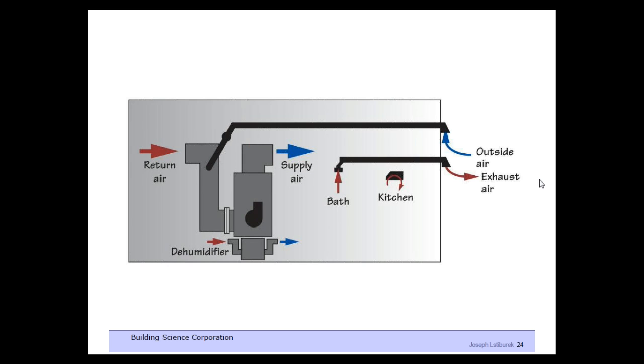South of the Mason-Dixon line, we're going to end up having to add supplemental dehumidification. The reason is that the loads are so low in these units and the outside air change rate is so high, the latent load is at the point where no typical coil design or air conditioning system is capable of handling it.